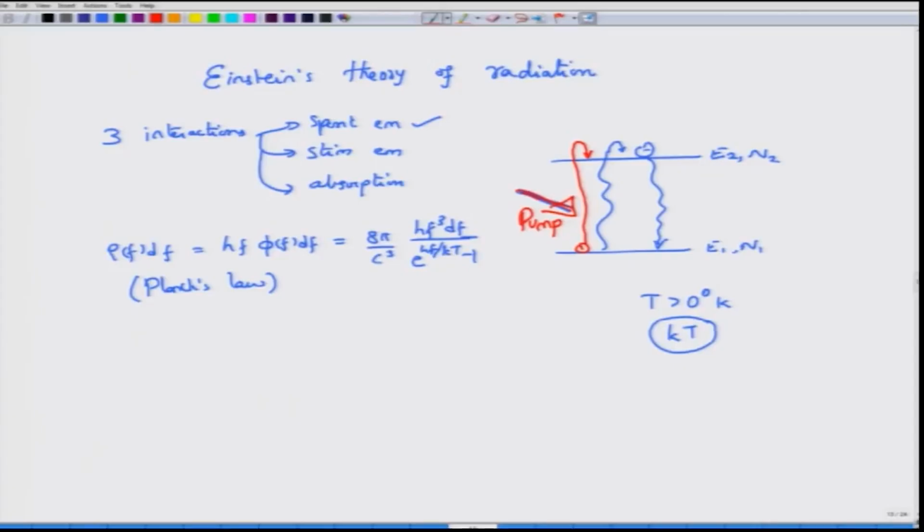But the semiconductor lasers do not really have optical pumping, they have electrical pumping. So, the idea is that you supply a certain amount of energy to the atoms which are in the ground state E1, so that when they absorb that energy, they can jump up to the higher energy state, or move to the next higher available energy state. And this process is called absorption due to an external pump being incident on the matter.